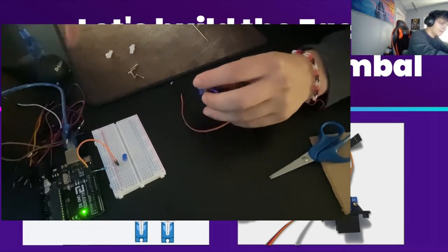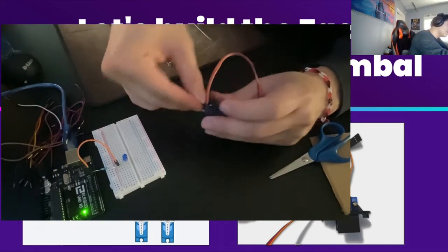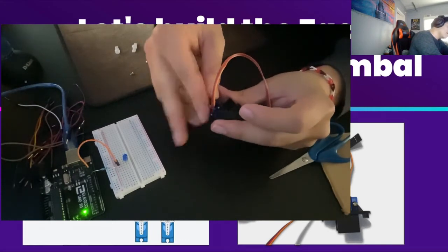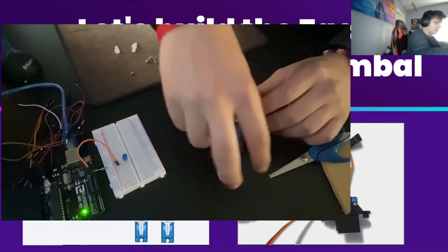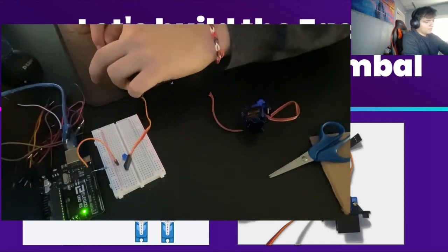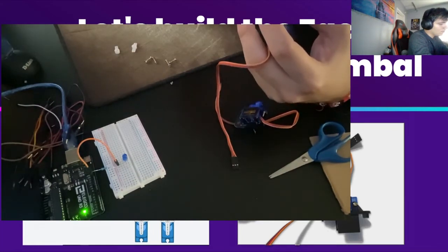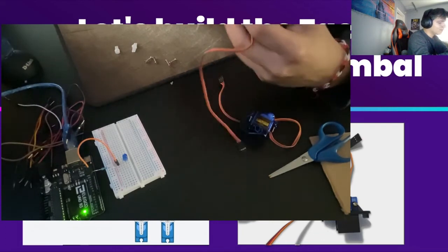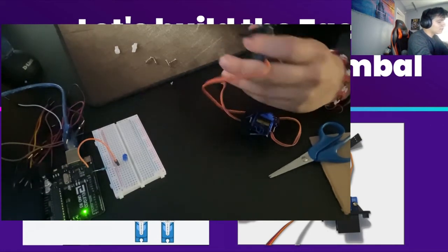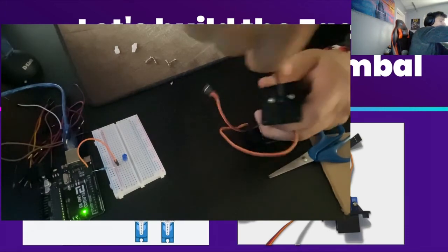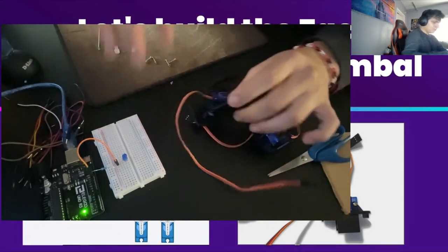We're almost done. Let's go ahead and finish screwing in this nut. Perfect. Okay, so we have this connected. One thing I forgot to do with you guys, we need to also add the screw that's going to make sure the servo doesn't move from the white plastic part that we added to it. So we're gonna get that small screw that also came in a little baggie with those servo parts, and we're gonna go through the middle of the hole and screw that there. So that now it's stuck in there and it won't move. Okay, so we're almost done.